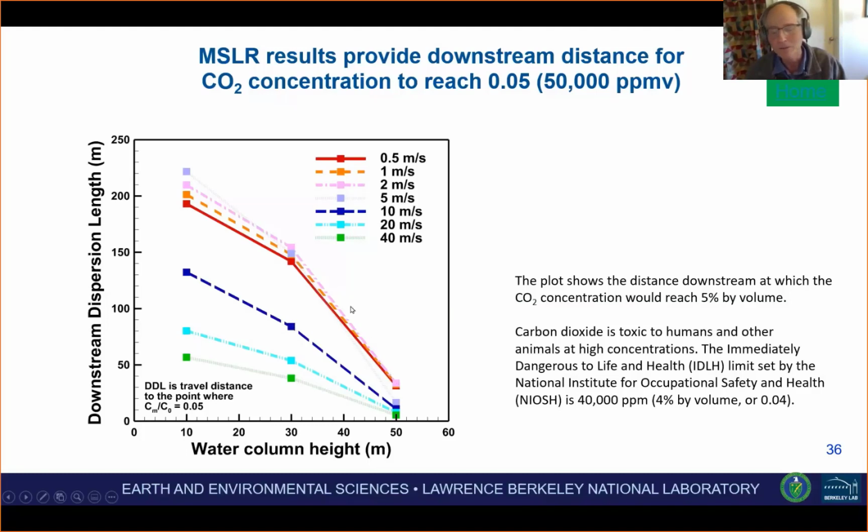So there's a reversal here that is along the lines of what I've been describing in dribs and drabs throughout this talk: when you don't have much wind, nothing moves very much. And when you have wind, it moves, and mixes. So there's sort of a trade-off, a nonlinearity here, where you extend the region of hazard, but then you reduce it as soon as the wind gets up to a certain height. And that's kind of seen in the nomograph, I think, by the curviness of it. There are some times there when this nonlinearity of dense gas dispersion shows up.